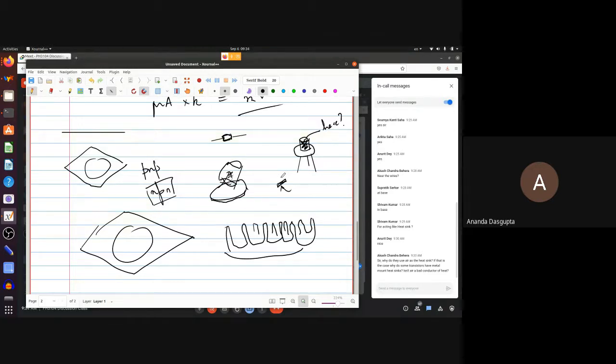Why do they use air as the heat sink? If that is the case, why do we? Well, actually, they do that. So when you say air as the heat sink, you mean why is there air inside? That's not used as a heat sink. I'm sorry if I gave you that impression. It's really hollow inside. The hollow thing is simply there so that you can use a lot of metal to give a large area. The same amount of metal, if it had been solid, would have had a much smaller area. The cap is hollowed out simply so that you can get a much bigger area. Area, of course, is useful because it helps you to radiate away the heat.